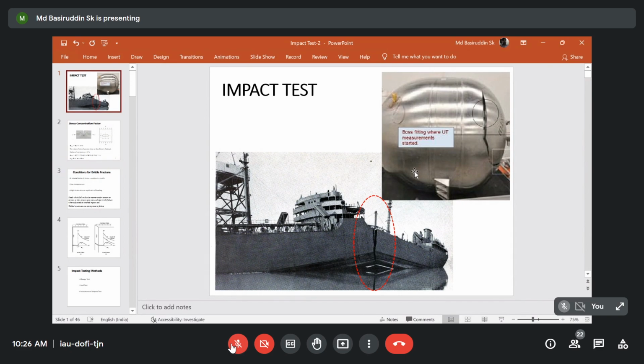Okay, and how do you know that the material has failed under ductile fracture manners? If you characterize the fracture surface thoroughly and carefully, then you will find some dimple kind of fracture microscopically. And macroscopically, if you see, then you will find some cup and cone kind of fracture. With your open eyes, by seeing those things, you will understand that the fractures generally happen under ductile fashion, because in those cases the loading rate was relatively slow.